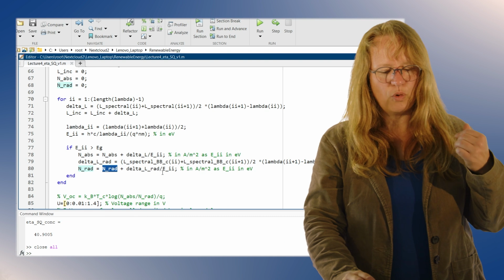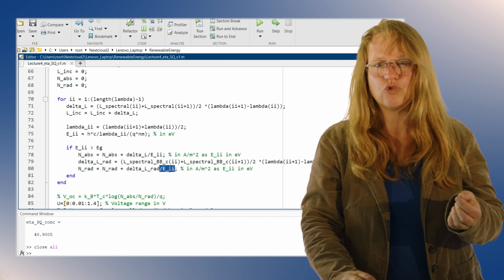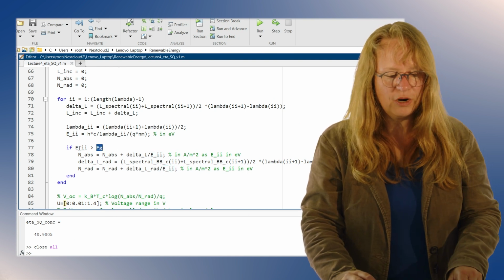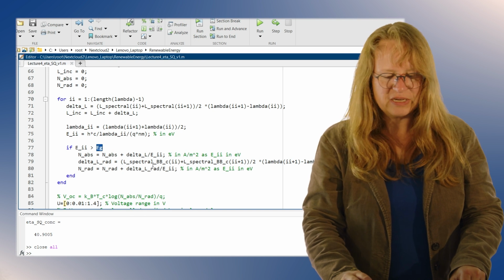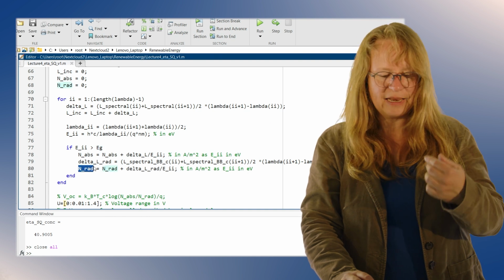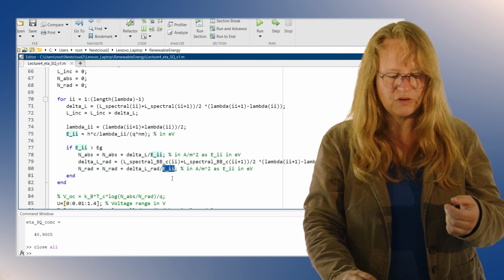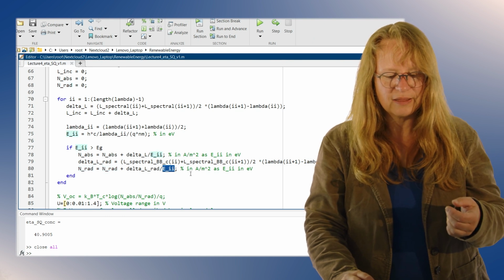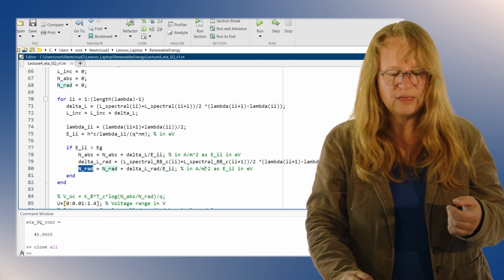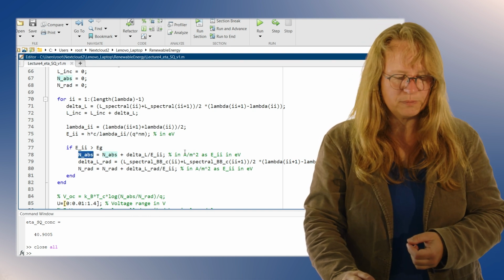I should also say, since all the energies here, Eg and also EII, are given in electron volts, I actually already have an additional Q in here. If we consider that it's already multiplied with Q due to this electron volt definition, the NRAD, the radiative number here, is actually already a current per meter squared, and also the N absorbed is already a current per meter squared, since the energy values are in electron volt.